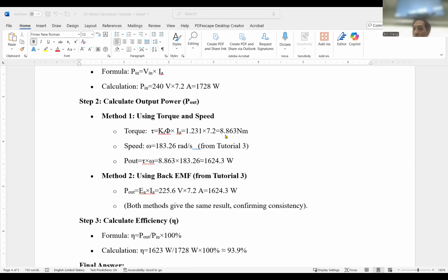But now we got a chopper. We already reduced the voltage from 300 volt to 210. So 210 should be really close to the back EMF voltage. So yes, bear in mind, 300 is really large compared to 205, but now we are only at 210. So this 205 voltage will be used to calculate the speed.